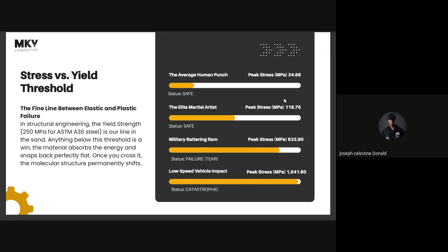Okay, then you start thinking, first things first, like I said, you now have variables, constraints, and a goal. Sorry, constraints. What's the threshold you are trying to meet? We're trying to keep it below 250. Okay, you've got your constraint. What variables can we change? Can we add more fillets? Can we add more reinforcement? You understand? Okay, you get that right. And then the goal, what are we trying to achieve? We want to make it stronger.